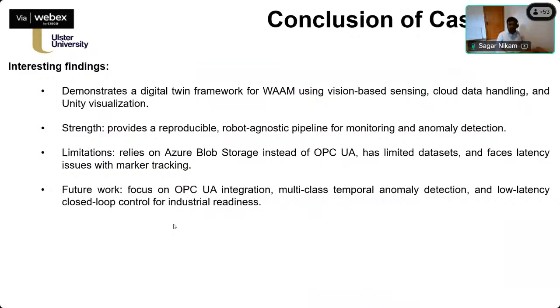As I said before, there is different future work possible in these case studies, like the control loop, sending the control back. According to the bed defects going on, you can control the robot arm. For example, if you want to maintain the robot speed, feed speed or traverse speed, you can send that instruction back to the physical machine so that it can eliminate the defect.